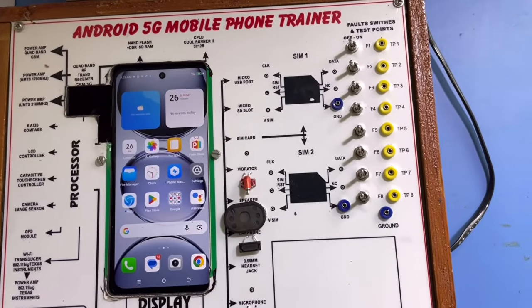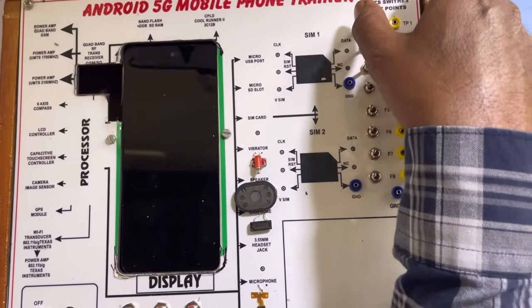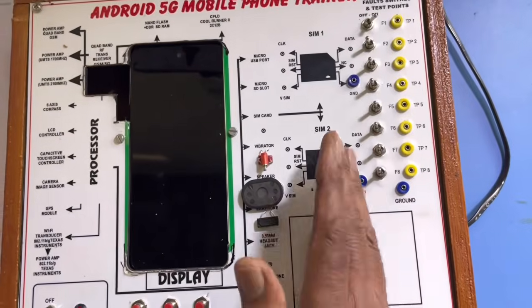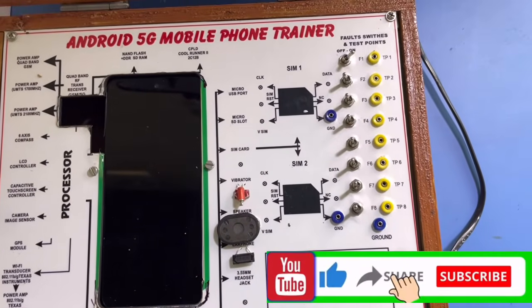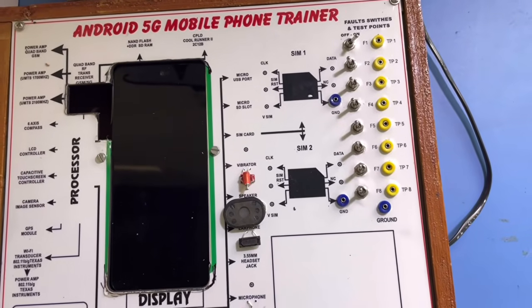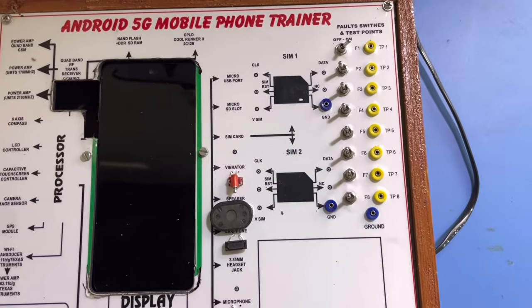Only the 5G network we shall use to introduce various faults. Now we shall introduce the first fault. F1 is introduced by taking the lever of the first switch to the right mode, and the remaining levers of all the switches to the left mode, to cut the ground of the control key section. In this case, see, there will be no display on the mobile. This is the on-off power. The mobile will not work.